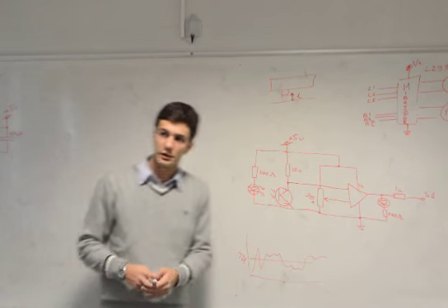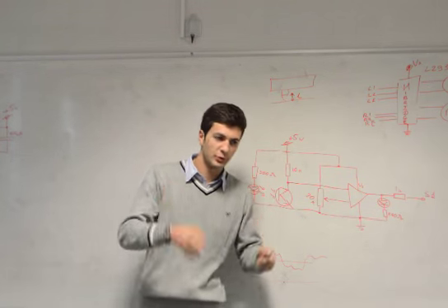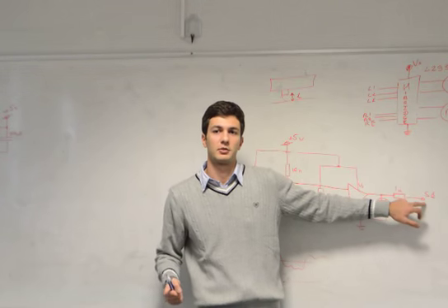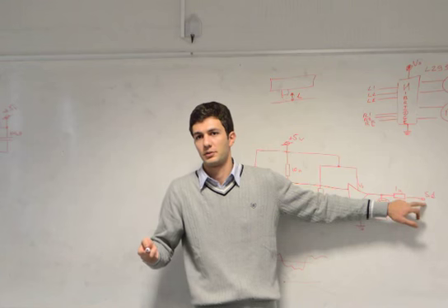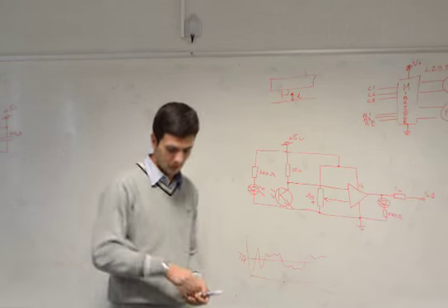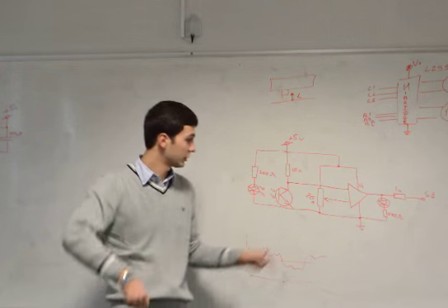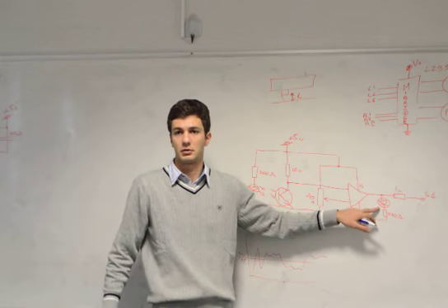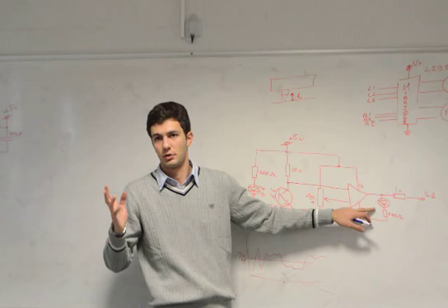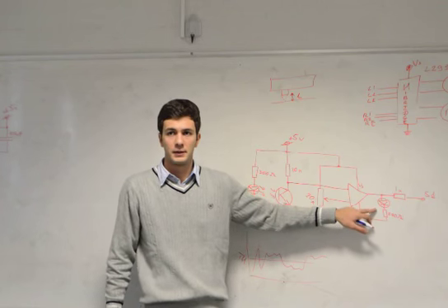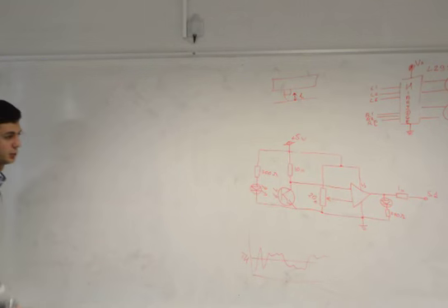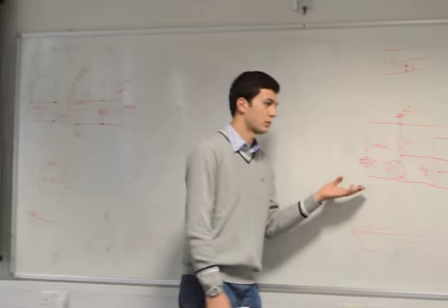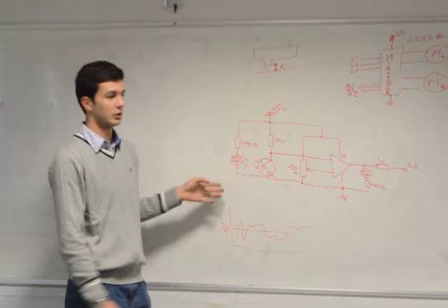So we actually don't have to go into the program and see what the input is. We just visually rotate the screwdriver on this potentiometer and see if the LED is lighting or dimming, or actually it won't dim, it will either go up or down. And we can set the white and the black. So this is the circuit for one infrared sensor.